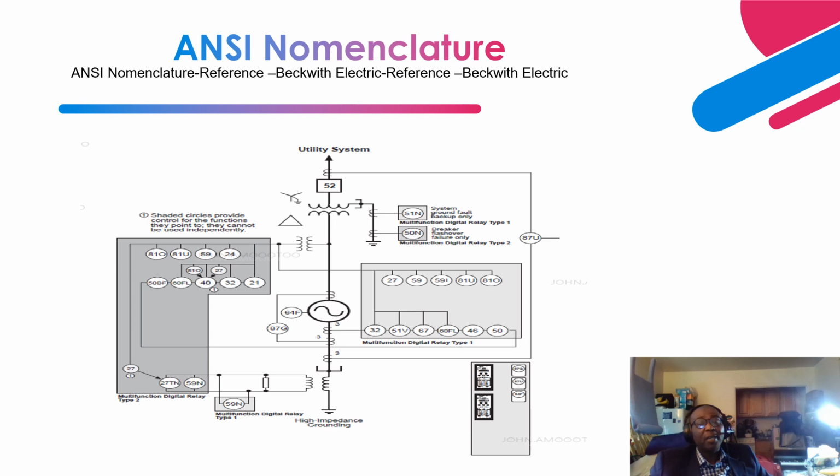When it senses that current flow after a period of time, it knows for sure that this breaker has not tripped. Then it's going to time out and activate other breakers in close proximity, especially breakers on the AC grid, to trip, to prevent the cascading flow of current into the AC grid.